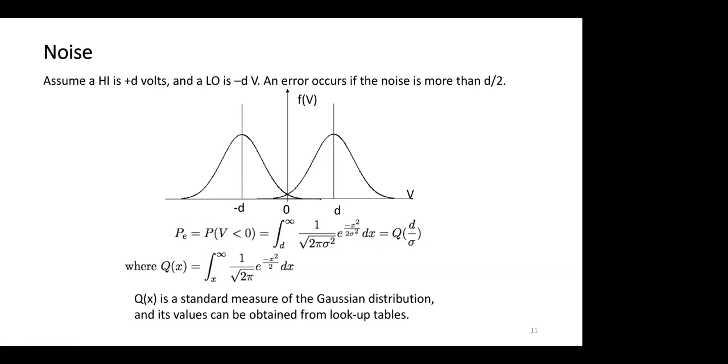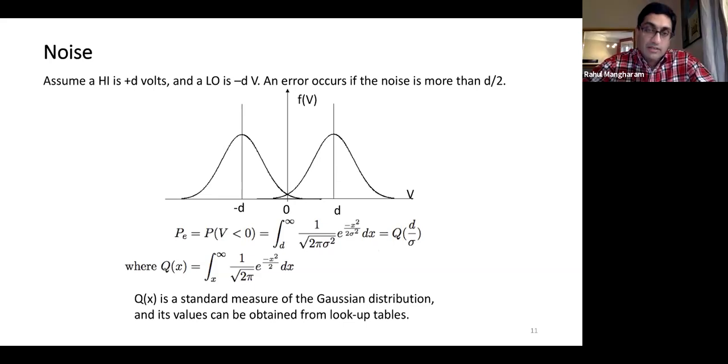Oh wait, I think it makes sense because the Gaussian distribution has a mean of 0. Now, if we're shifted by d, the error actually occurs going from negative infinity to d, and it's symmetric, so you can flip it to d to positive infinity, I think. Yeah. Did everybody understand that? Okay, that's good. Yeah, and so essentially this Q function is measuring the probability of this error, right? That is crossing this, right?